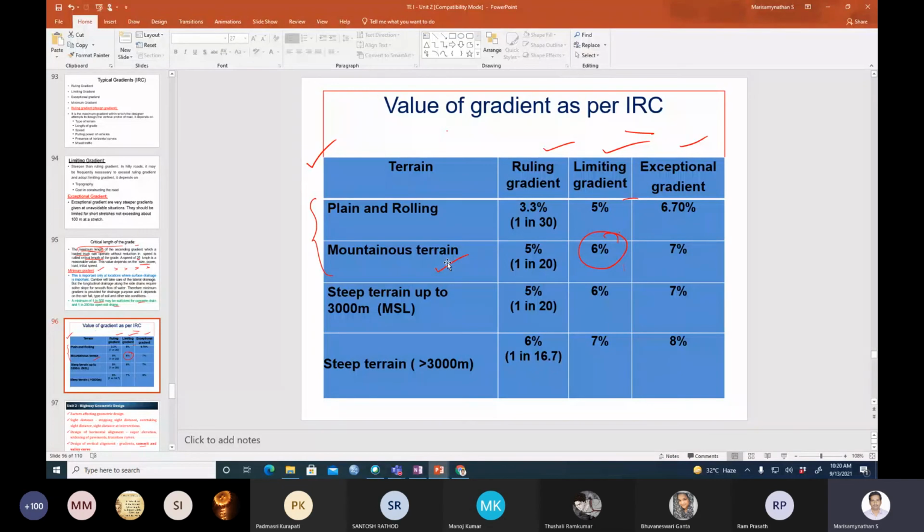In these three cases, the first is the allowable rate of centrifugal acceleration, with equations based on the C value. The second is the allowable rate of super elevation, the E value. The third is the estimation using the IRC empirical equation.